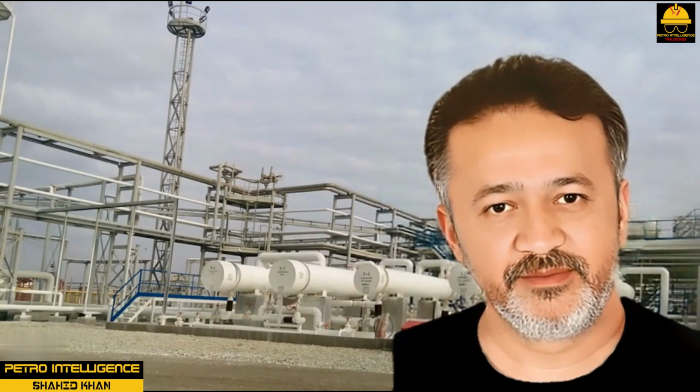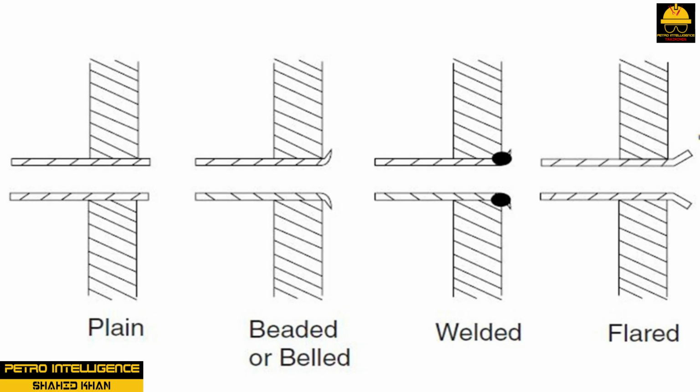Tube sheet. Tube sheets are often described as fixed or floating, single or double. A tube sheet is a flat plate to which the ends of the tubes in a heat exchanger are fixed by rolling, welding, or both. Tube sheets have carefully drilled holes designed to admit the end of a tube and secure it to the plate.